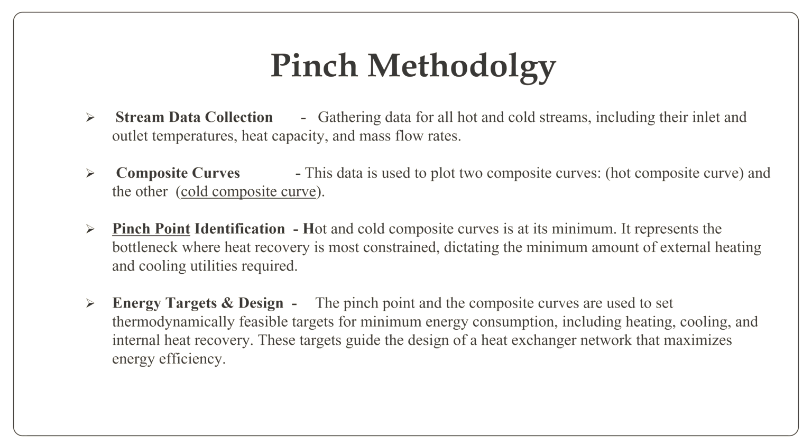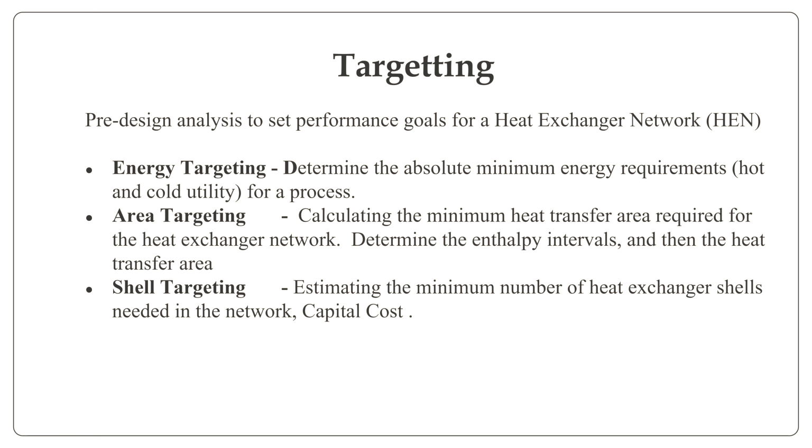Energy target and design. After plotting the pinch point, we can target the energy for maximum energy recovery and minimum energy consumption. For designing the heat exchanging network and targeting the area of various units like shell and tube heat exchangers, we can reduce the cost and also increase the energy efficiency of the process. Targeting is the main thing in pinch technology. It is a pre-design analysis to set the performance goals for a heat exchanging network.